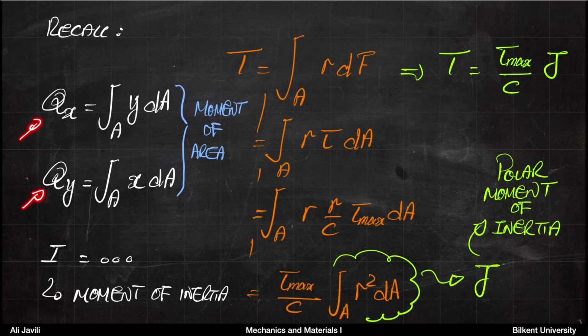Qx and Qy, we call them moment of area. So if you think of them as first moments of area, because you have just the distance times area. Now, if you have higher powers, if you had power 2, you would talk about second moment of area. And that second moment of area connects more to something like moment of inertia. Okay, so you should not confuse this.